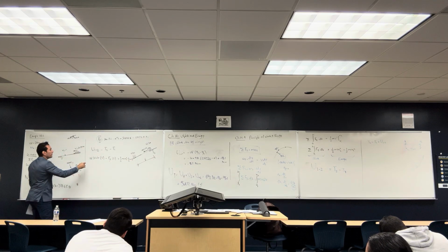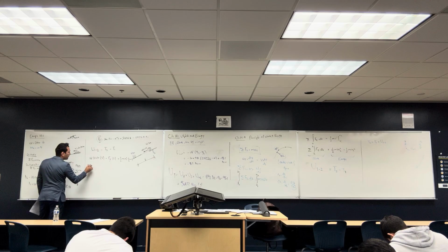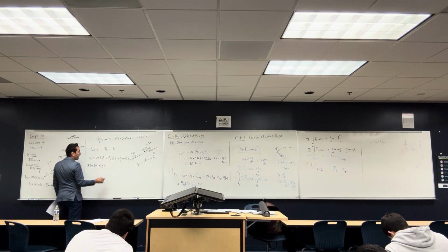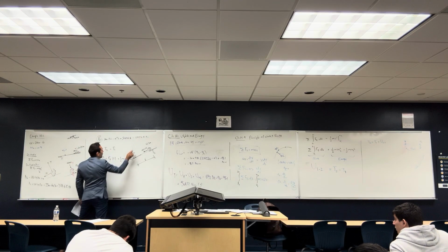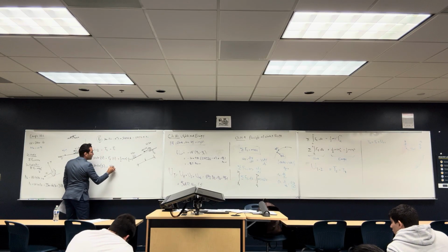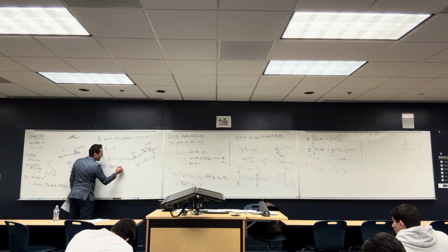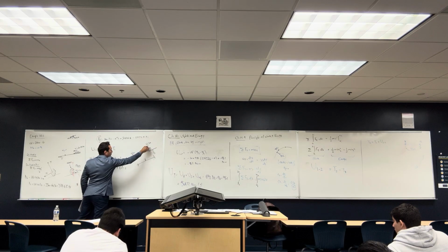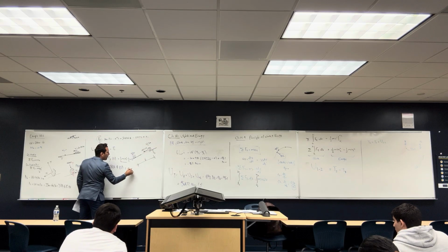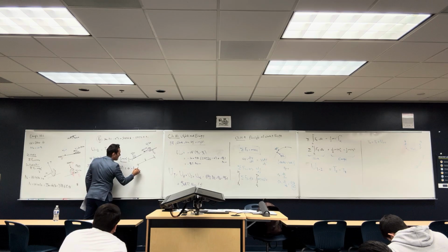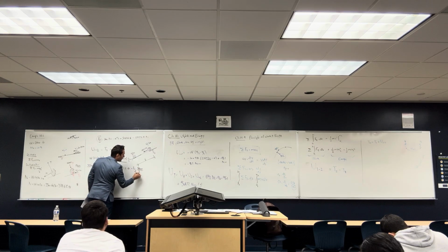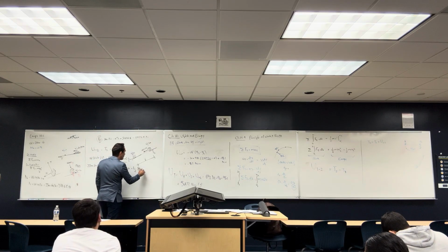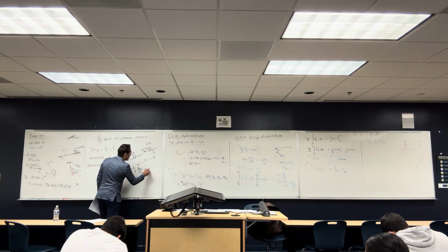Okay? So let's substitute. I have the weight of the car is 350 pounds, sine 10, multiplied by S, which I don't know. Friction is 1723.4 multiplied by S. For mv2, I know that v2 is equal to 0. v1 is equal to 20, so this is 0 minus 1 over 2, the mass is 350 over 32.2 because the weight is in pounds, so I need to convert it to mass, multiplied by 20 squared.